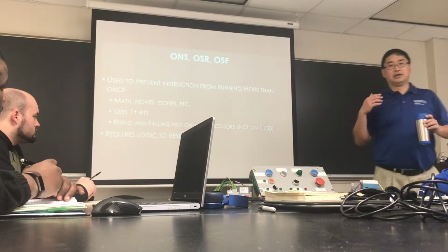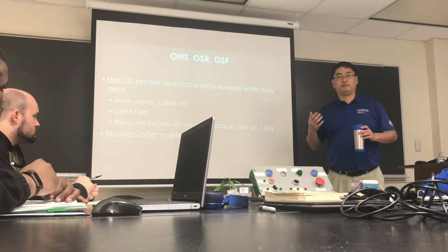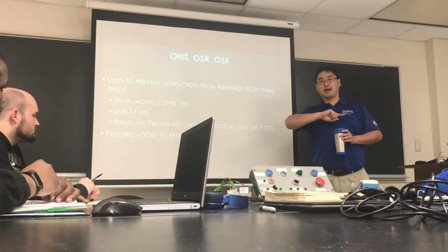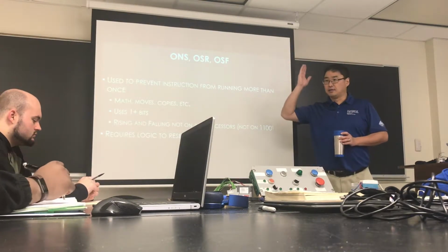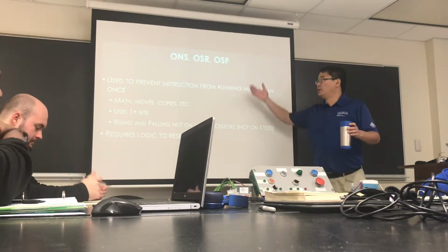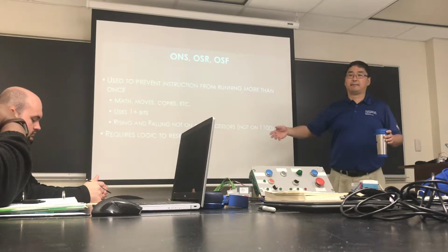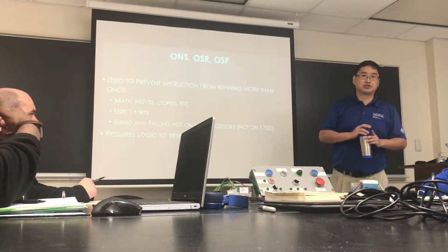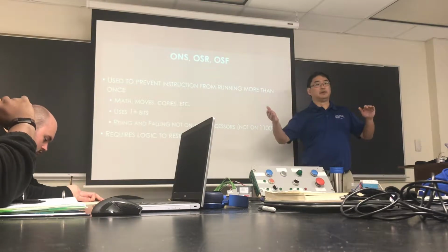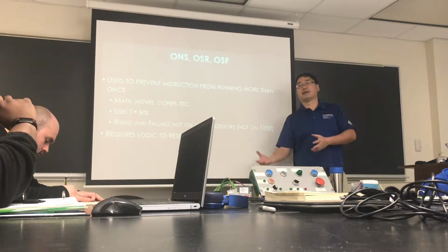one-shot works is when that rung evaluates from false to true, the one-shot allows it to process once and then prevents it from processing again. Now, I could write my own instructions to do that, but it's easier to just do the one-shot. But after it's run, you have to turn it off or you can never get back to that rung again.